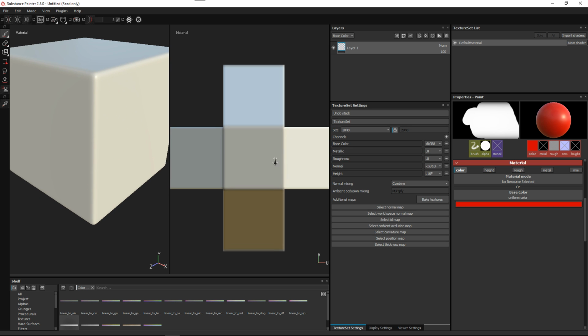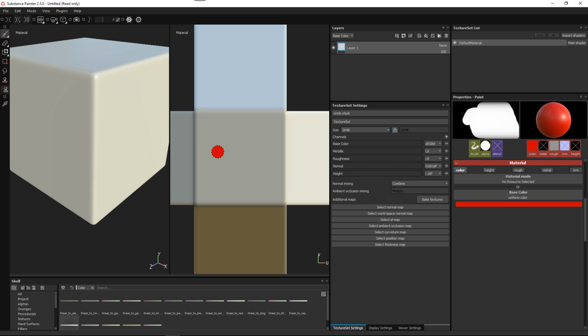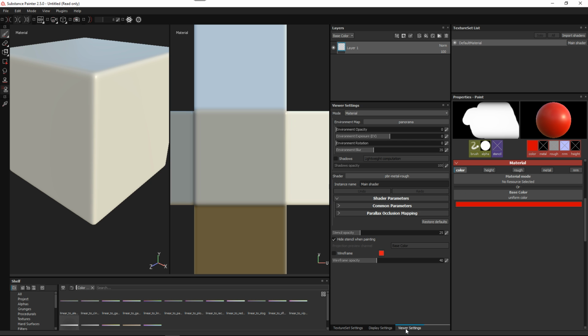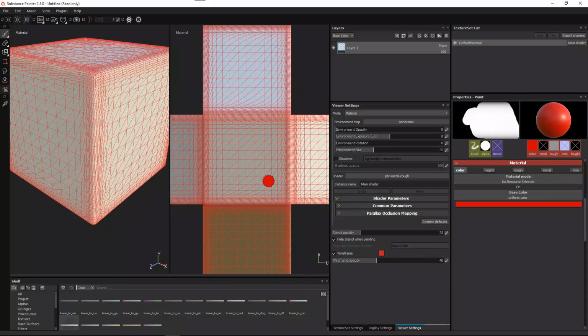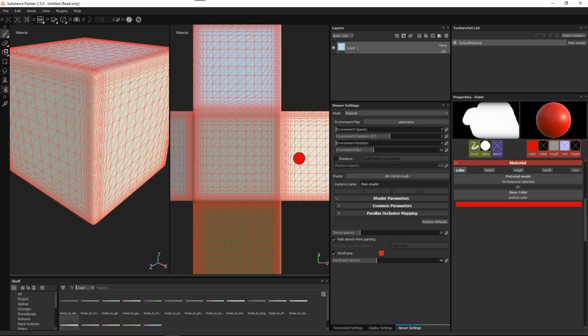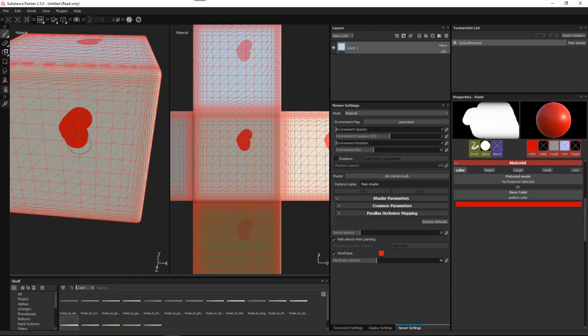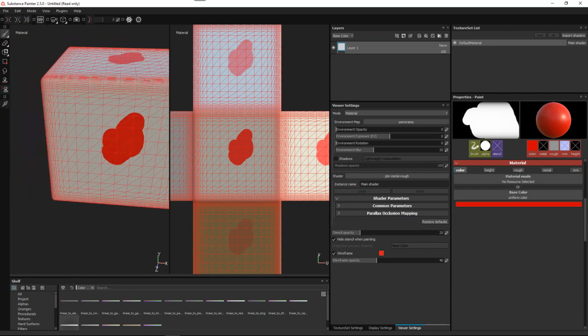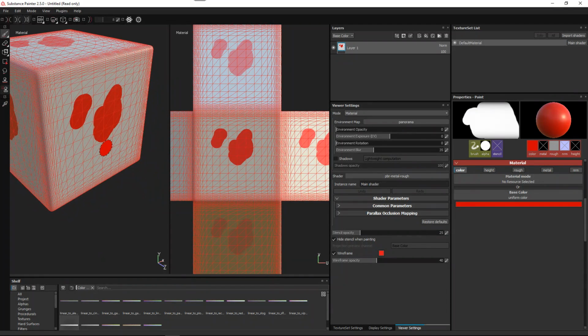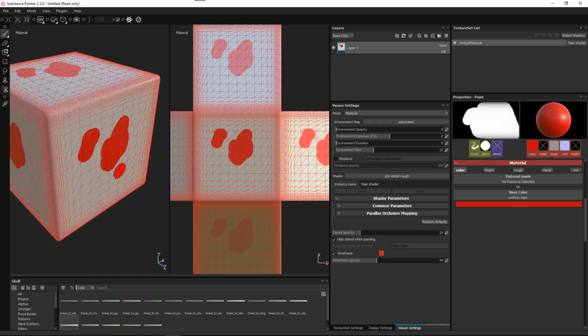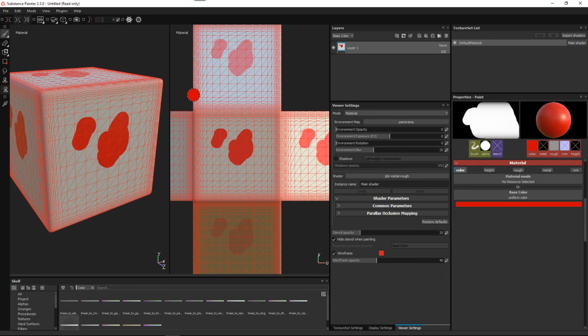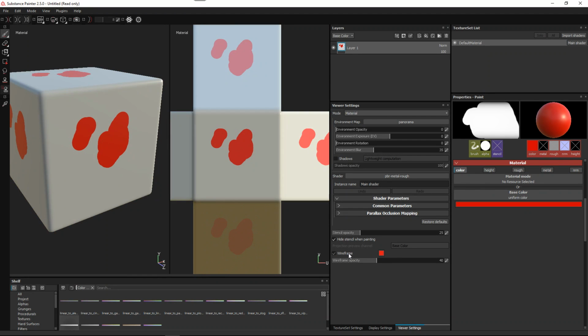But what I wanted to show was how the UVs are laid out. In this case, you can see this is the 0 to 1 space here. Let's go to my viewer settings and enable my wireframe. Again, this is the 0 to 1 space, and you can see that a lot of these faces are moving outside of that 0 to 1 space. So in Painter, if I try to paint on this, it's not going to paint because it's outside the 0 to 1 space. I just need to find the face that's actually in the 0 to 1 space, which is here. So long story short, no features there. I just wanted to illustrate that in case you're new to Painter and you're watching the stream. All right, so let's turn all this stuff off here.